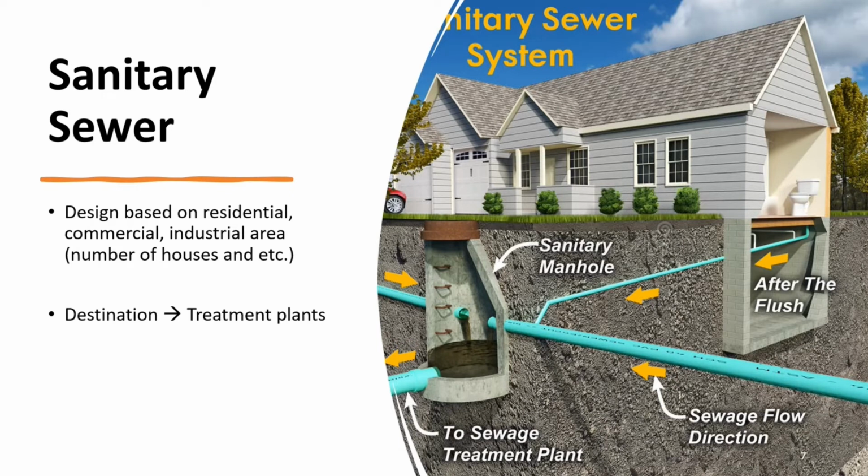And from those two holes, when we have overland runoff flowing over the manhole lid, a lot of the storm water will flow into the manhole. If it is flowing into the storm manhole, it's fine, because that storm water was supposed to be in that storm sewer anyway.